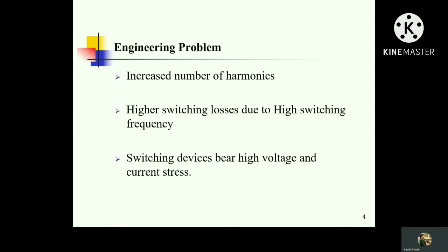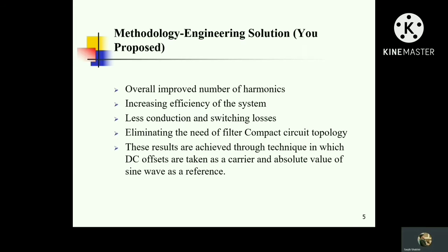What is the engineering problem? Increased number of harmonics, higher switching losses due to high switching frequency, and switching devices bear high voltage and current stress. The methodology we chose to implement our project gives overall improved harmonics, increased efficiency of the system, less conduction and switching losses, eliminates the need for a filter, and gives a compact circuitry topology.